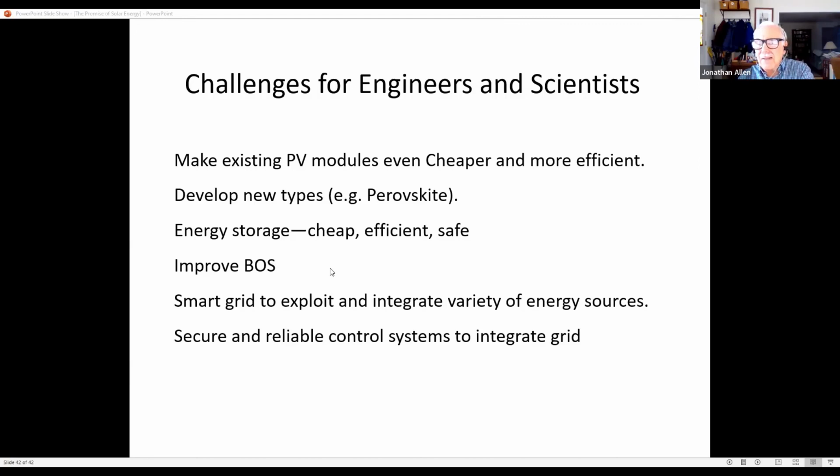Our hope was that given the very high cost at that time of crystalline silicon, you would just put up more amorphous and you'd come out economically superior. But as the people in the industry, particularly in Japan and China, made the cost of crystalline and polycrystalline silicon orders of magnitude cheaper, that argument ceased to have much weight. So amorphous silicon is pretty restricted in its uses now. It's usually used for very small installations where a little extra area doesn't cost you much. But that balance of system and extra area really made it non-competitive. Does that pretty much answer it?